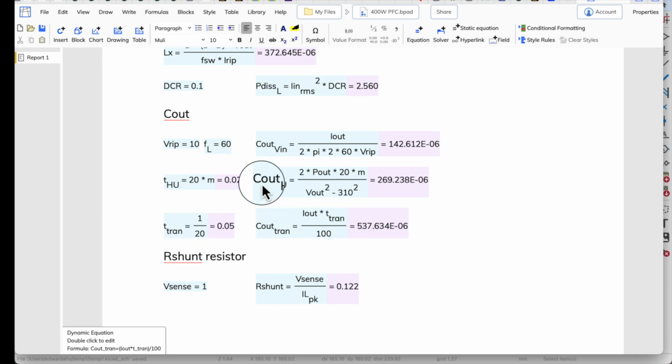Now, this is really a worst case, guys, because I'm saying it can drop 100. Maybe it can drop even a little bit more. And also maybe you're not going from 0 amps to max amps, right? Probably not. So this value here, 500-something microfarads, is really a worst case. But between these three equations, you can see how you can cover all cases of transients, whether it's input voltage or output transients. So if we're around 500 microfarads or above, then we should be solid, okay?